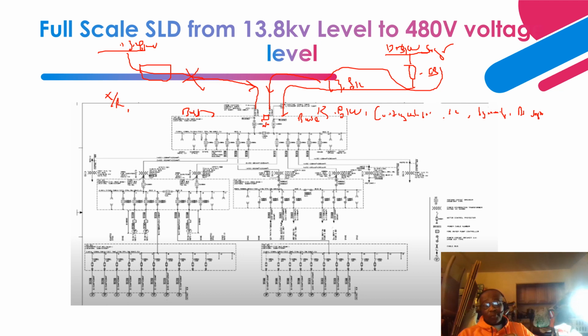That is the peak part of the fault, and that determines the asymmetrical short circuit capability, based on the DC offset, right? So this happens during the first quarter cycle of the fault. The fault basically peaks, and then it tapers, right? There's a DC offset value based on the X over R ratio up to the point of the fault.